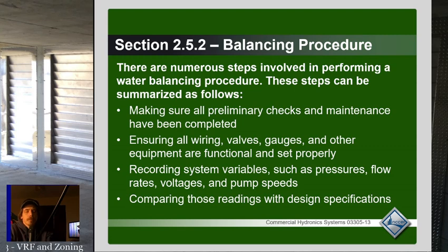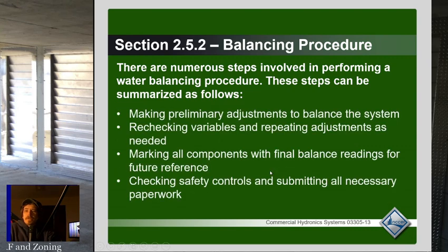And if you're doing outdoor air reset, you've got to make sure the boiler system temperatures are proper for each outdoor temperature and the curves are set right. And you've got to make sure you're providing enough flow through each of the individual system components in the system. So yeah, it's important to make sure that your balancing matches up with the original engineered design, whether you did it or an engineer did it.